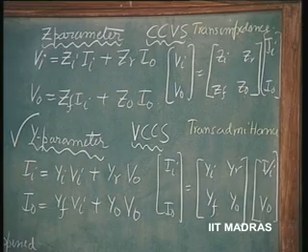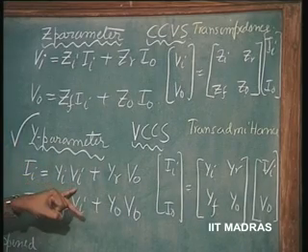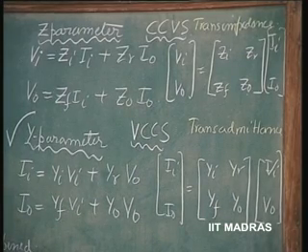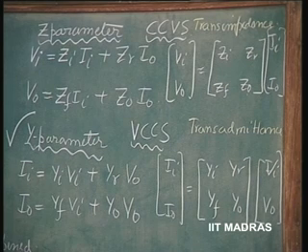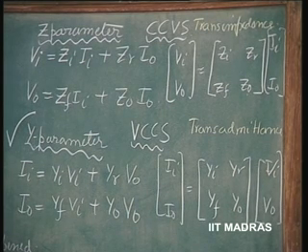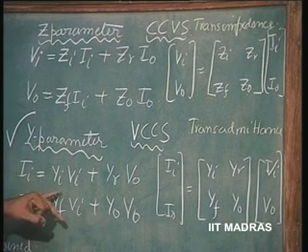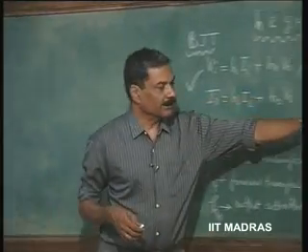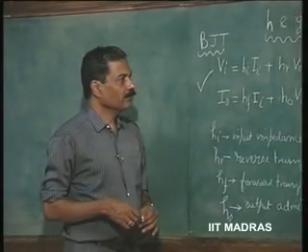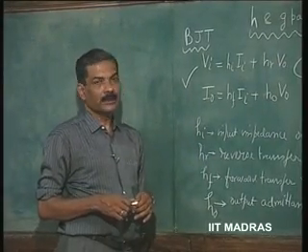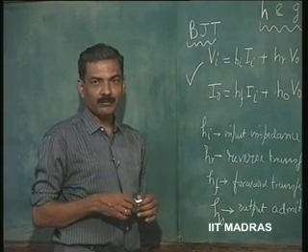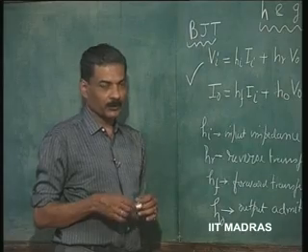And these parameters are nothing but admittance parameters, and capacitors which are stray capacitors can be simply added on to their admittance, okay, as j omega C. So, most of the stray effect is due to capacitors, and that can be simply added to this admittance. So, that is why these parameters are very important parameters in practice, which are measured in most of the designs, and there are a variety of bridges which can directly measure these parameters for any two-port network.